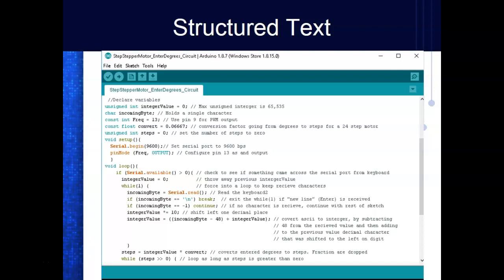We'll demonstrate one called Logic Pro, which basically simulates a modular PLC, a 500 series PLC. But you never actually generate a machine code program, but you can play around with it to see if your program would actually work if you actually put it into a real PLC. And a lot of your PLCs come with simulators. So they don't actually generate a true machine language program, and they never go to the actual PLC itself.